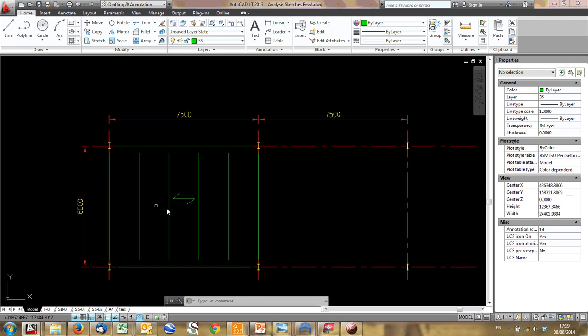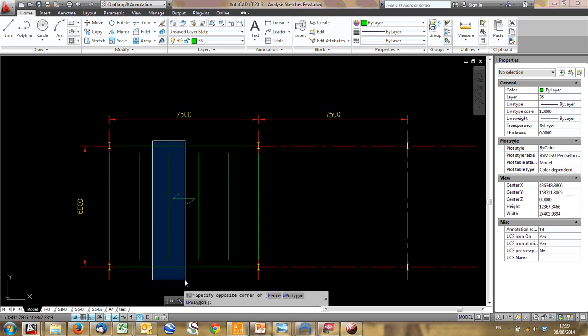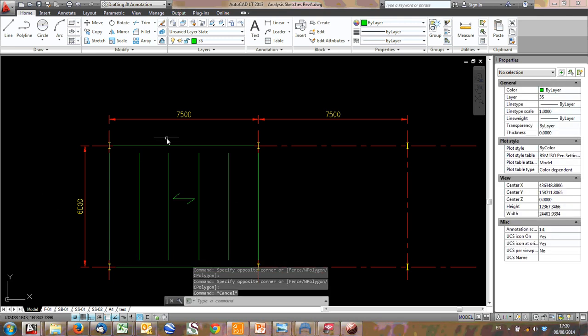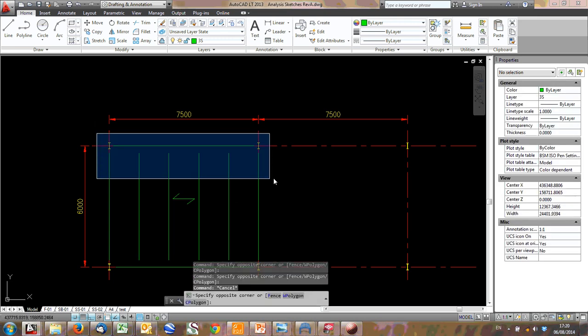For instance, let's say this is a panel that shows that it's a one-way spanning slab, not a two-way. It means all the load, if I was designing this beam, the load area would be that. I can get a UDL, design the beam, design this beam, etc. Well, they'd all be the same. And then those will put reactions onto that.